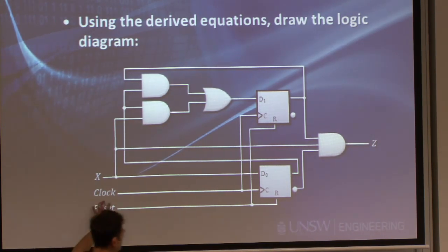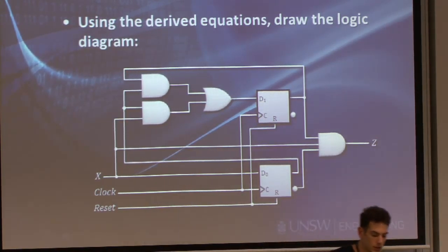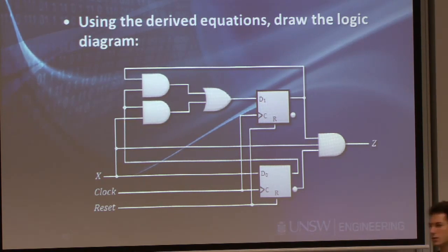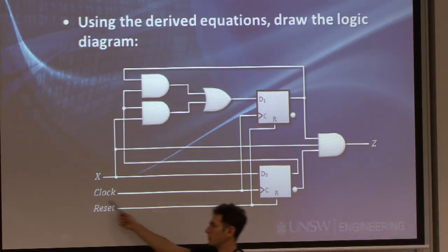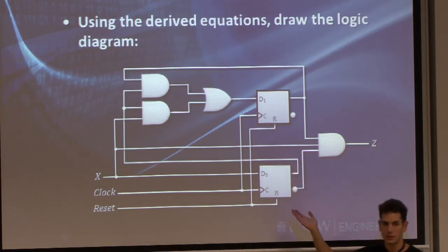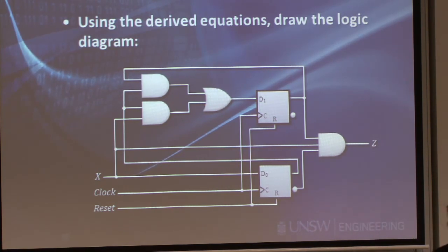We don't usually use this reset signal during the normal operation of the circuit. We will usually turn on the circuit, assert the reset signal once, get usually 0 and 0, reset implies zeros. So 0 and 0 into those flip-flops, and then start our clock that will start driving our circuit according to the machine.